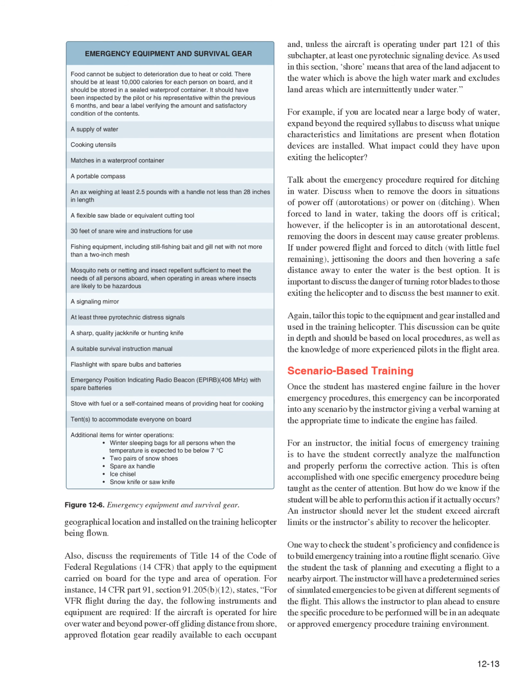It is important to discuss the danger of turning rotor blades to those exiting the helicopter and to discuss the best manner to exit. Again, tailor this topic to the equipment and gear installed and used in the training helicopter. This discussion can be quite in-depth and should be based on local procedures, as well as the knowledge of more experienced pilots in the flight area.